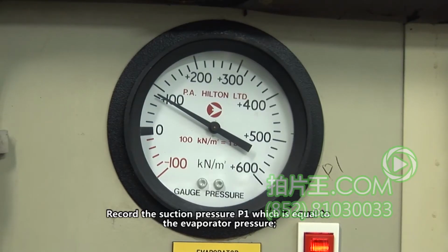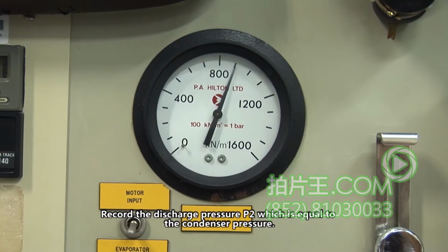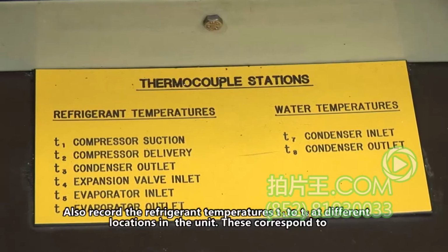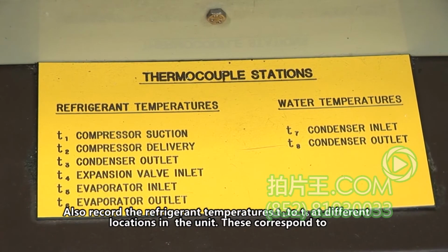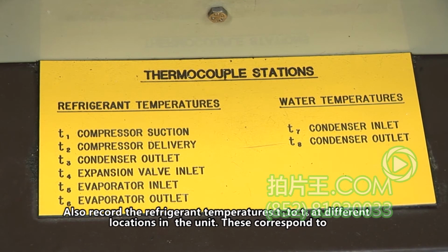Record the suction pressure P1, which is equal to the evaporator pressure. Record the discharge pressure P2, which is equal to the condenser pressure. Also record the refrigerant temperatures T1 to T6 at different locations in the unit.